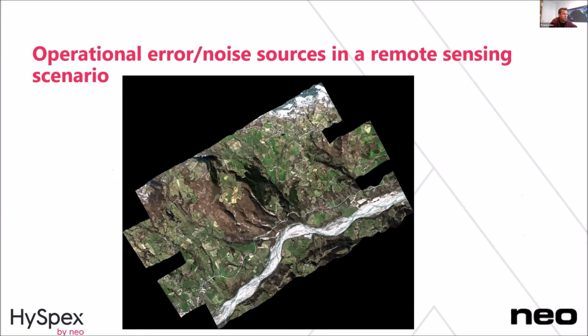For all the optical distortions that happen due to temperature, pressure, EMC, and vibrations, that's based on your design, how you design your hyperspectral camera, how temperature is distributed in your camera, how it's affected by having an open hatch and cold air on one side of the system and not on the other. All that is extremely important in the optomechanical phase and in designing your optics.